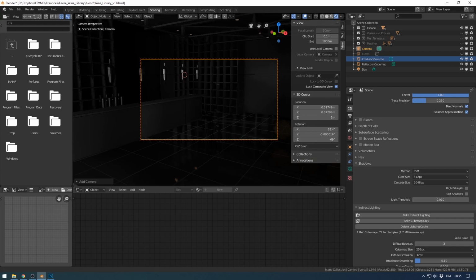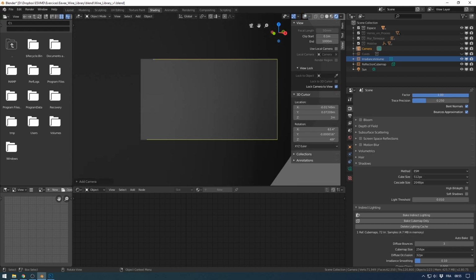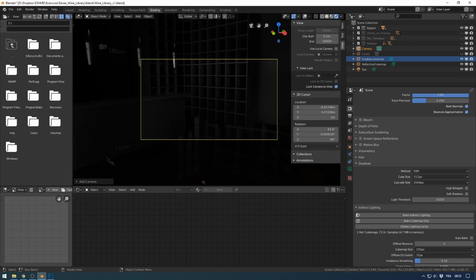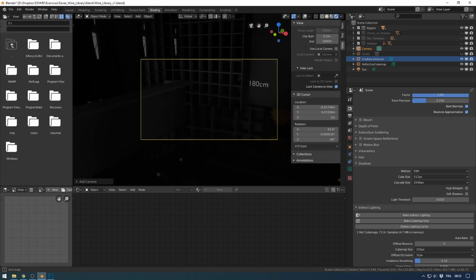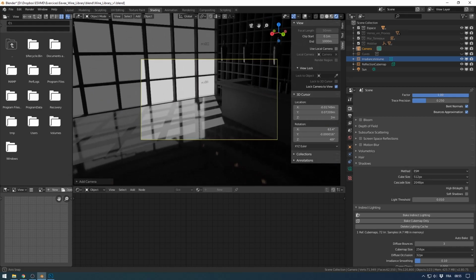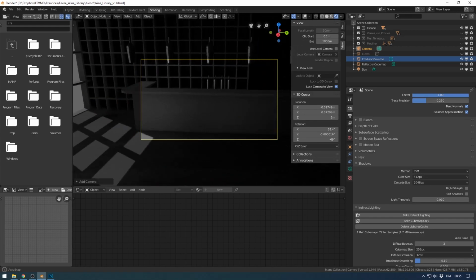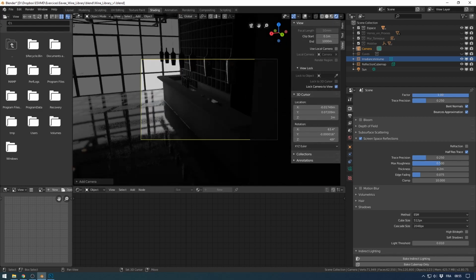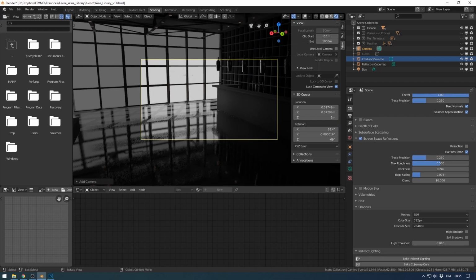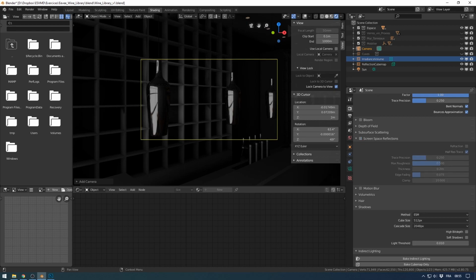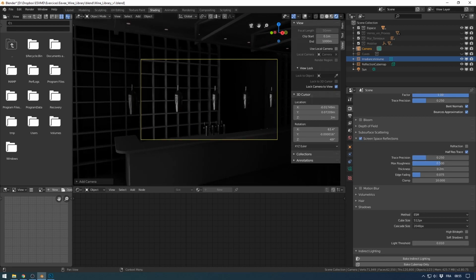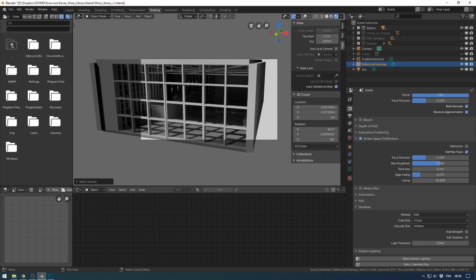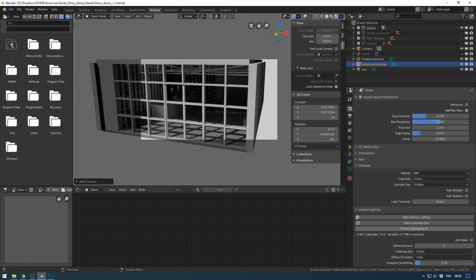You could see that I have strange reflection on the ground here. You could see that it's not correct. So I have masked objects in the viewport here, but you could see that on this element, the storage here, it's not really good. The reflections are not correct. Okay, probably because of the scale of the cube map. I usually like to blend the screen space reflection with this, and usually it works. So normally I use screen space reflection and a reflection cube map, and for me it has worked pretty well. I will delete the light cache here.